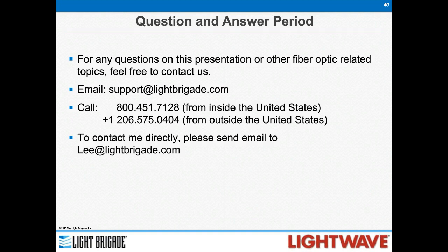All right, we answered the index of refraction. Is that the length for the cable or the fiber? As I said, that's the fiber length, and you're going to have to adjust for the cable length depending on the kind of cable you have and how long this is. So again, we can help you with that. Manufacturers of your test equipment can help you with that as well. And a lot of cable manufacturers can help you answer that question as well.